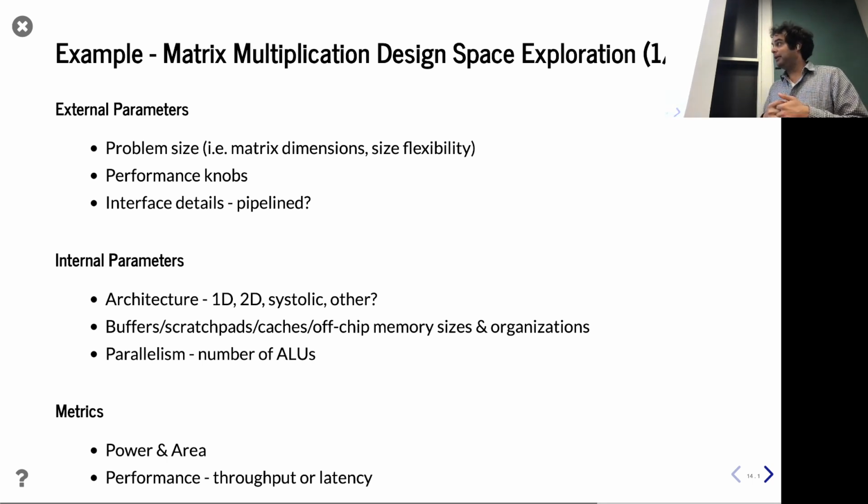So what matters? You can imagine, for a hypothetical design, if someone tells you, I want an accelerator that does a 128 by 128 matrix with 8-bit data types, maybe you can say, I can do that completely on chip. You do one design. Someone comes to you and says, no, I don't want that. I want 1,000 by 1,000, and I want you to do as many of those problems in parallel. Well, then maybe something more GPU-like and bigger, using off-chip memory, et cetera. So the problem constraints are really going to shift you, and it's going to change what the right answer is.